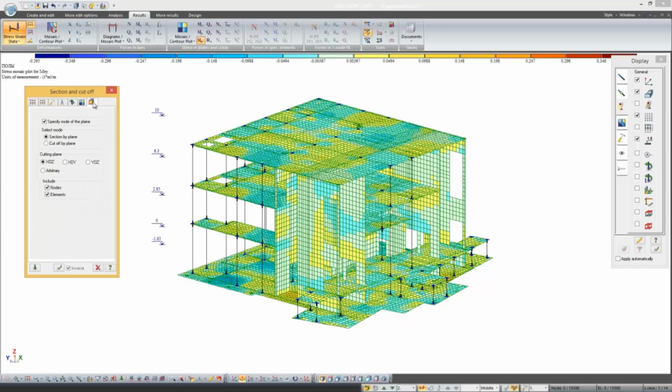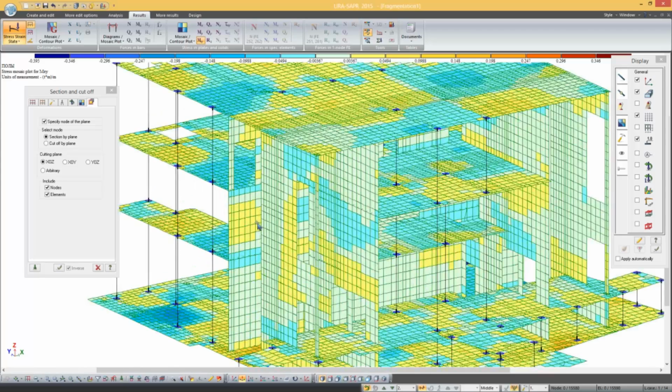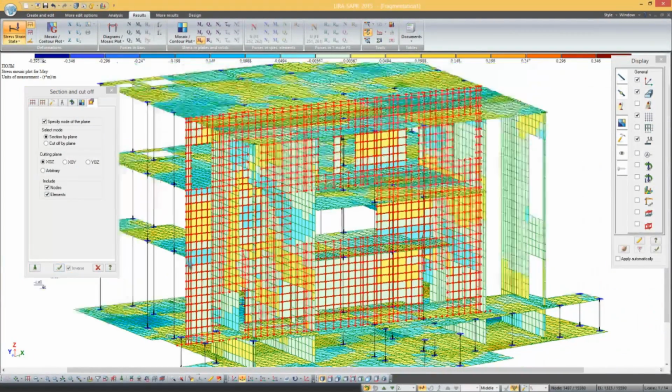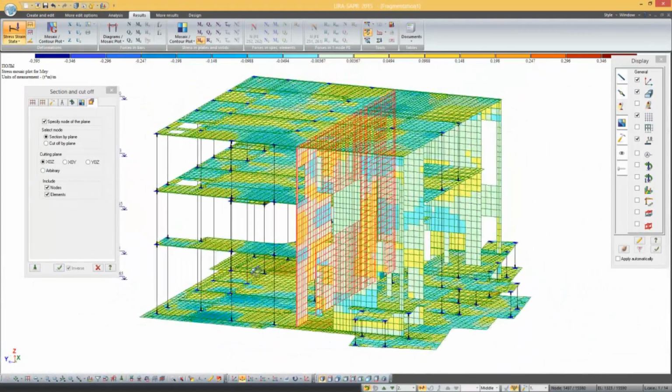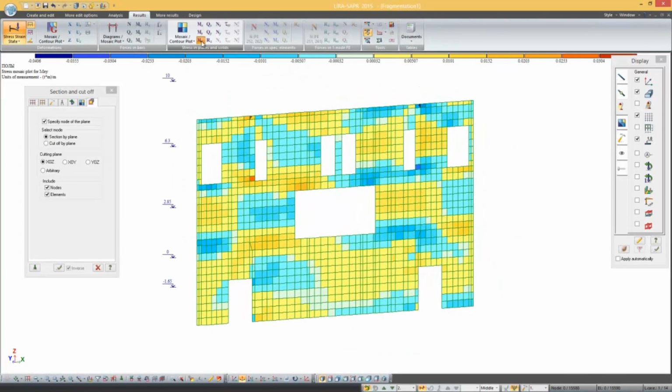For instance, we have to fragment the stiffness diaphragm that is located in the XOZ plane. Everything is pretty simple. To do this, we need to click on any node that lies in the plane of our diaphragm and click the Apply button and execute the fragmentation command. Then we begin to analyze the forces of our diaphragm.